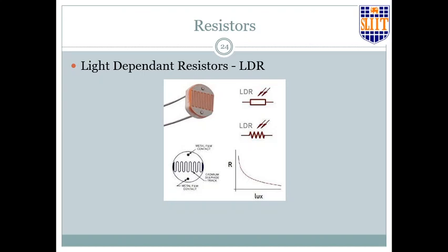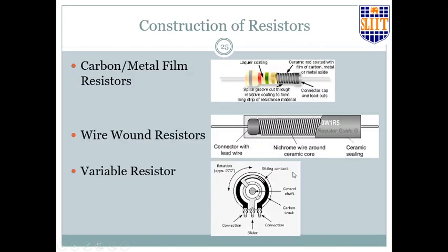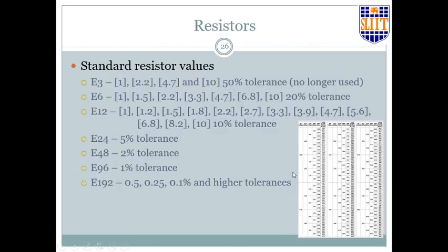The symbols are given in here. Right? We went through this. Alright. The resistor values, standard resistor values. Now you can't find any resistor, for an example, if in a calculation you got 101.25 as the resistance value. Will you be able to find it? No. Right? So you will have to stick to the practical values that are available.